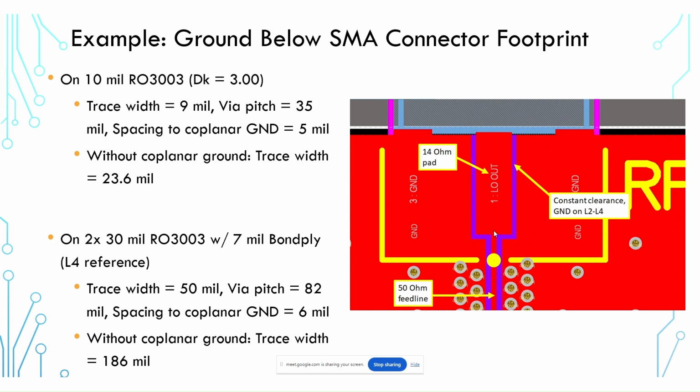Now, when you're operating at very low frequencies, this is an issue with RF design just generally. When you're operating at very low frequencies, we're really not worried about the impedance of this pad. And that's because of input impedance considerations. And again, maybe that's something we discuss in an RF design session. But here we have our 50 ohm line, and then it's coming into a 14 ohm pad. And the interface between this line and this pad creates some reflection.